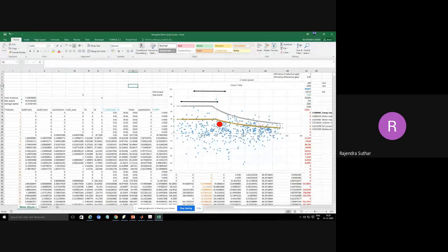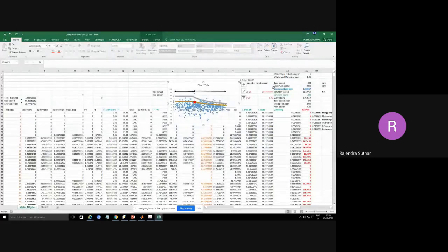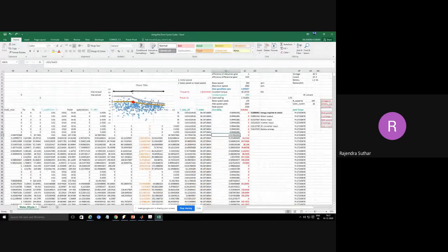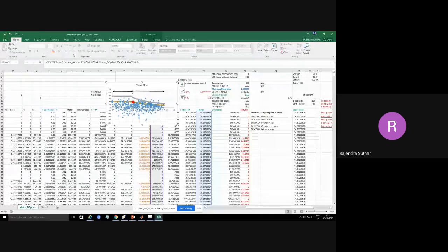We get the velocity profile and then we use this vehicle's specifications, and from the velocity profile we find out the torque requirement for that drive cycle for every instant. And now we have the torque data, and then we have to define our motor's rating. Here you may see we have two graphs. One is shown in yellow, one is shown in silver.